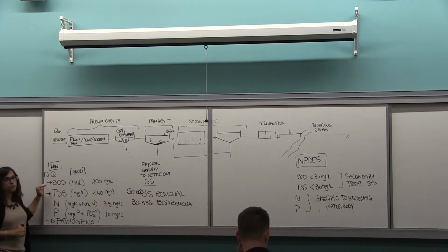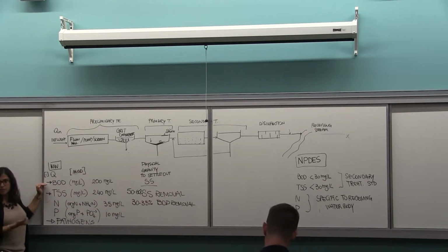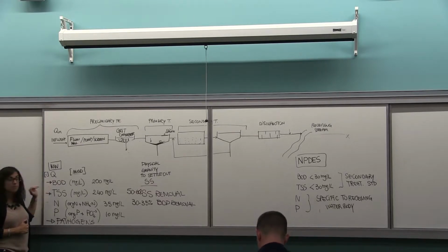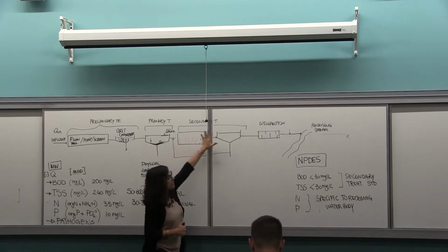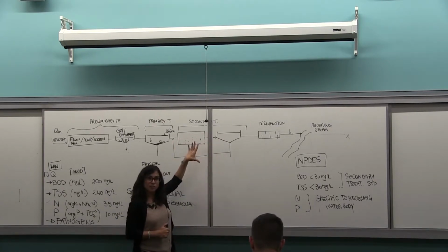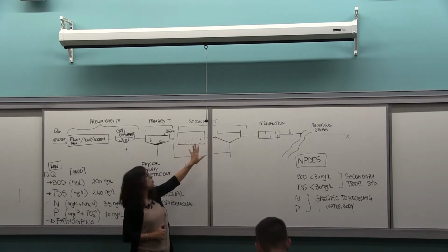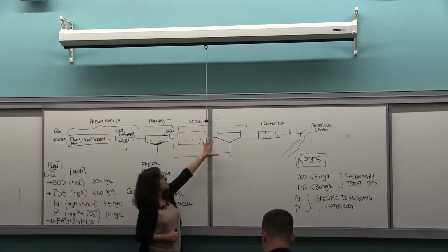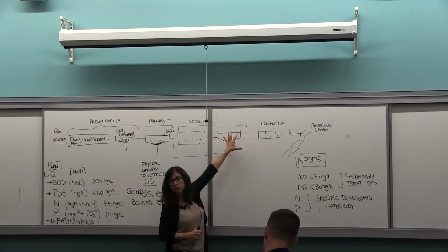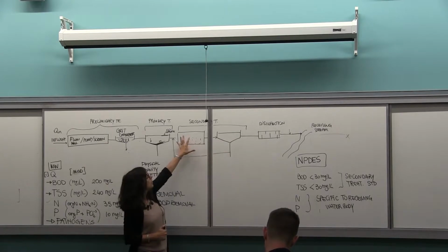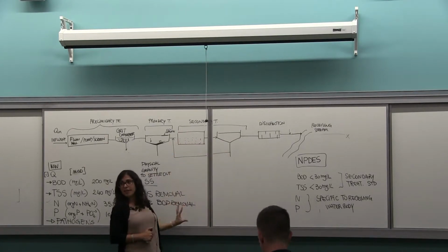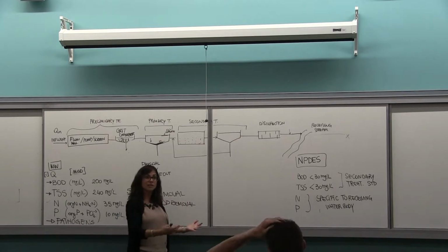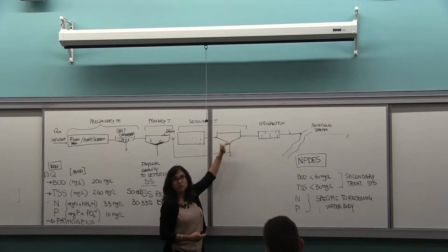We still need to remove some other important contaminants, the BOD, the organic content. This is done in what we call the secondary treatment. It's a combination of biological process and physical separation, where we have bugs that eat the organic, make up solids, and the solids settle out in a sedimentation.